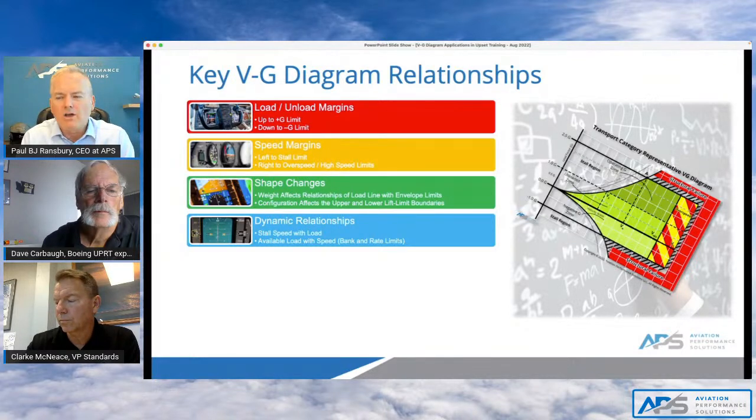So a good example of that is somebody asks you what your stall speed is. Very often you're just going to repeat exactly what the 1G stall speed is. Probably a better answer would be, under what load are you referring to? Because your stall speed can be at any airspeed all the way up to maneuvering speed. And it's important to understand that as pilots, we control our margin of safety away from the stall. And we're going to talk about that in a second.